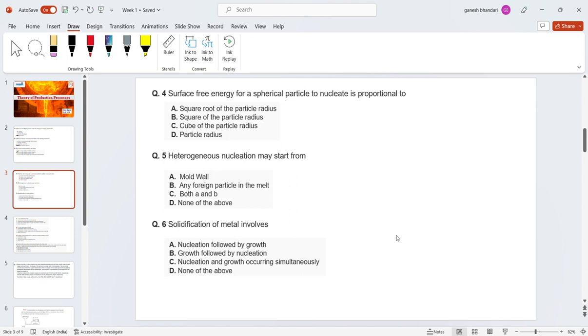Okay. There are more things about the soldering mechanism. You can also read about what happens during soldering. During soldering, at the junction point, intermetallics form. However, after a particular depth those intermetallics are not present, and lead and tin are present in a particular proportion. So lead-tin solder also comes in particular ratios like 60-40, 67-33, and 90-10, where 90 is tin and 10 is lead.